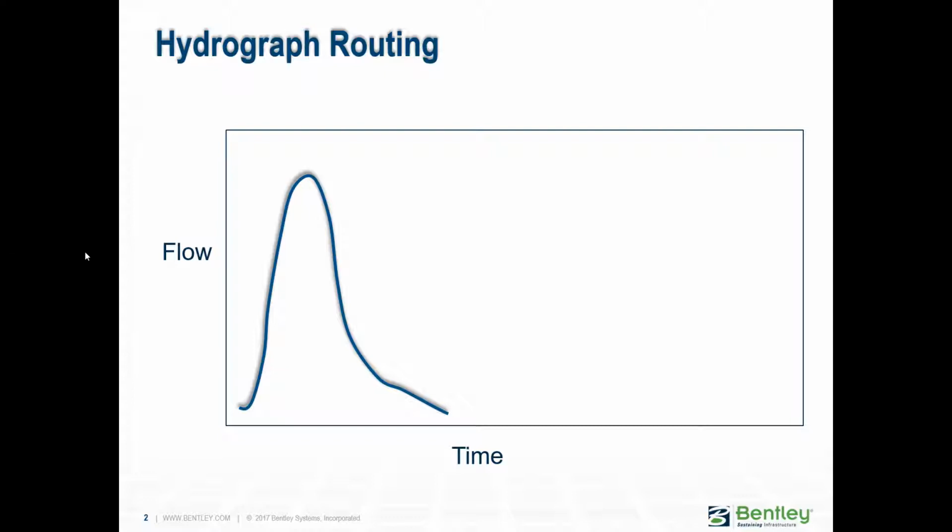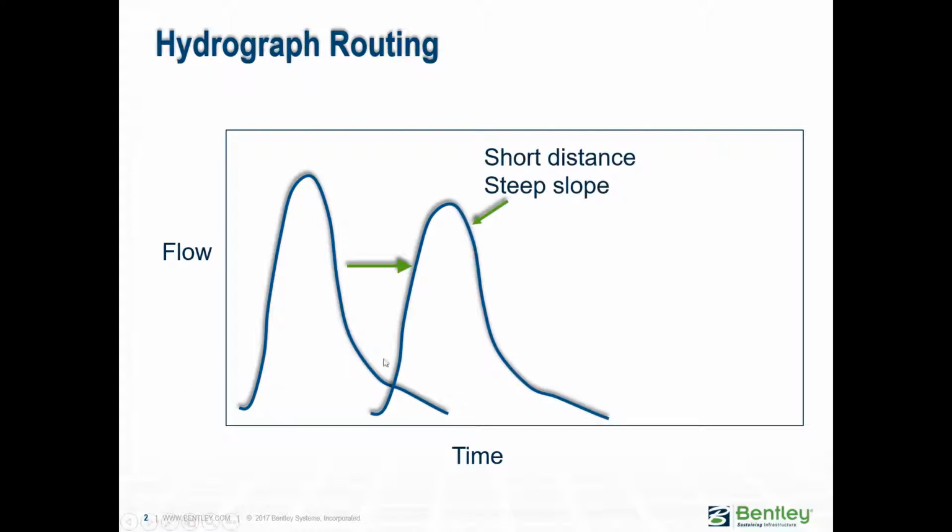So here is a typical situation that we have. We've looked at hydrographs quite a bit by now. So if you go to the first manhole in a pipe run, the most upstream manhole, and you pour, let's say, a bucket of water, it would look something like this, right? So flow increases and then decreases. And then let's say you run really fast downstream, just kind of following the water, and you measure there again what the flow is. You're going to see something like this, right?